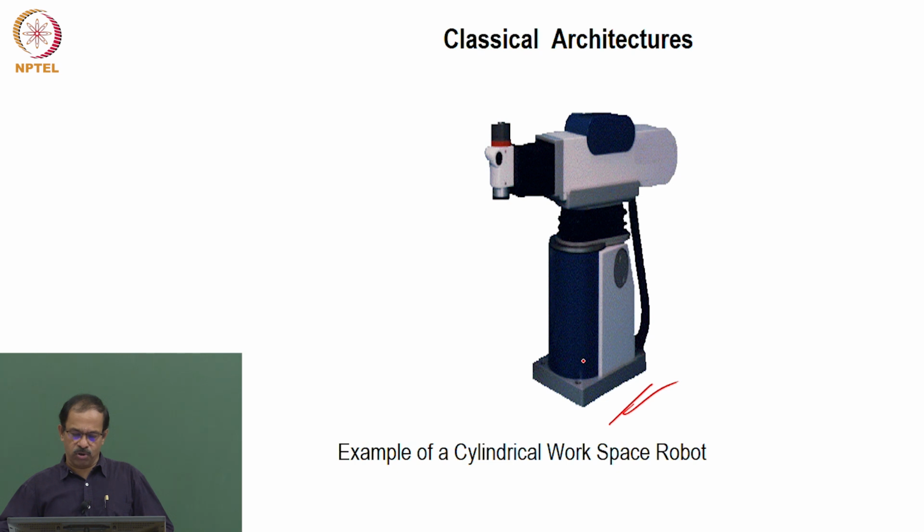They may get corroded or get damaged easily, because you can see there will be protection on this surface. These are all provided with bellows to protect the slides from getting jammed due to environmental pollutants or something like that. And they should always be very smooth, otherwise you will get a lot of motion difficulties. So that is one of the difficulties with the prismatic joints. So you need to have proper protection for them, otherwise they will get damaged.